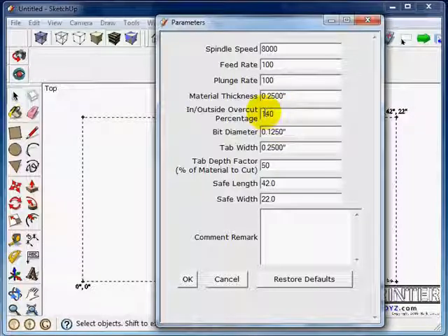There's an automatic overshoot, so it's set at 140%, so it'll make sure that it cuts through all the waviness of the fan fold heights. You could change this. You could set 100 here if you wanted it to be exact, but of course it wouldn't cut all the way through. Remember, this is only for inside-outside cuts. On the flat printer, it doesn't matter so much. On a regular CNC mill where you would hit into the table, you would want to keep this at 100.